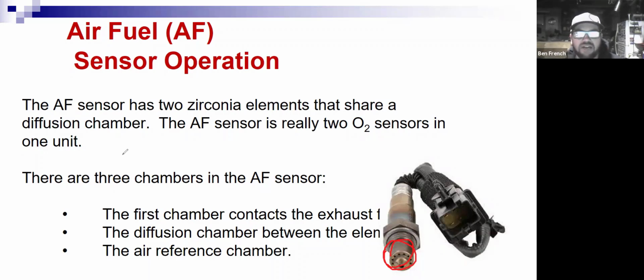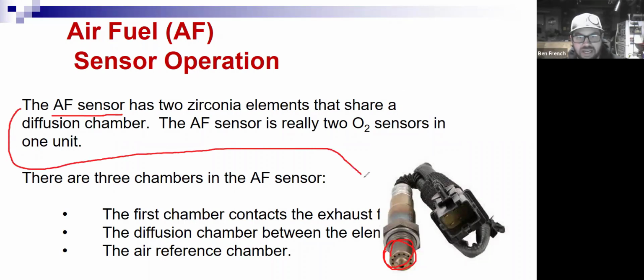Anyways, with air fuel ratio sensors, I tend to rely more on the air fuel ratio monitor. Seems to give me pretty good data on them. And I always test to make sure that I have power and ground to the heating circuit and that the wiring is good. And if I'm setting codes for the air fuel ratio sensor and it doesn't respond to rich or lean conditions, it's a pretty safe bet that the air fuel ratio sensor is at fault. So, all right.